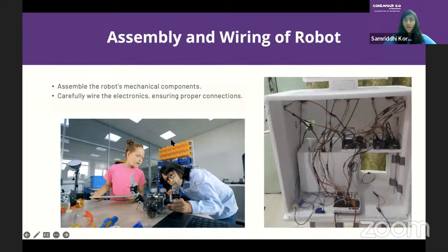I mean, unless you solder it, which is advice that I would give you all. But if your wires get loose, what are you going to do? You'll have to find out which wire goes where, right? So label all of them together, and immediately when you go, just connect them together.